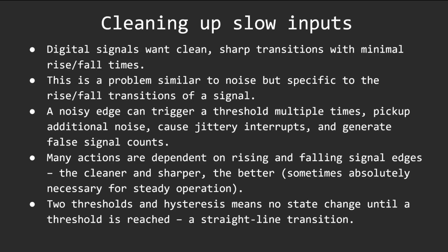Another use is cleaning up slow inputs. Well, what do we mean by slow inputs? Digital signals want clean, sharp transitions with minimal rise and fall times. This is a problem similar to noise, but very specific to the rise and fall transitions of a signal.